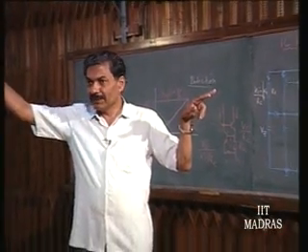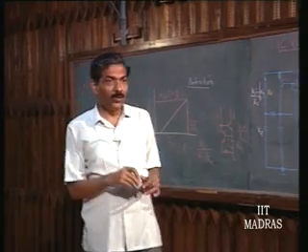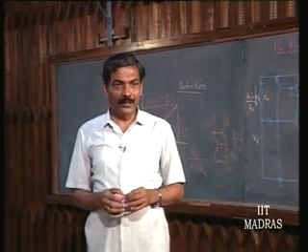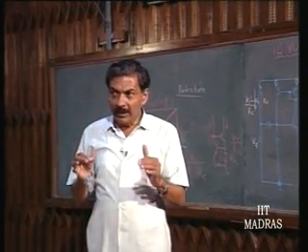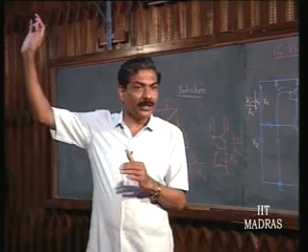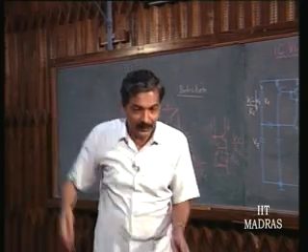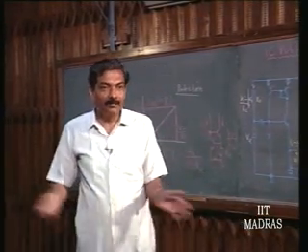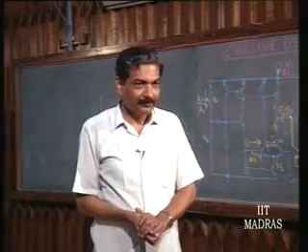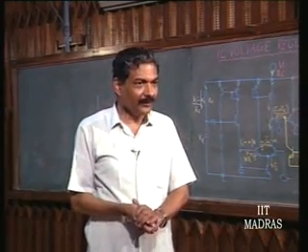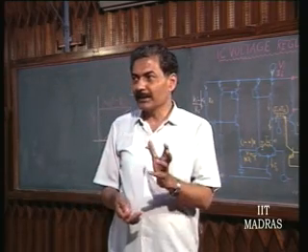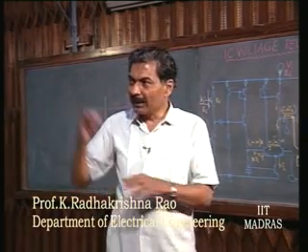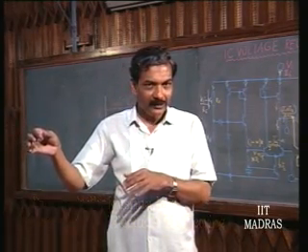Okay. So, we will discuss in the next class this Foldback short circuit protection, which is the one that is to be recommended in regulators which are going to be remotely located, where if a short circuit occurs, I do not come to know immediately, and poor regulator might by that time conk out. So, this kind of thing particularly becomes necessary for the remote locations, where until somebody comes and repairs it, it should be in this mode.